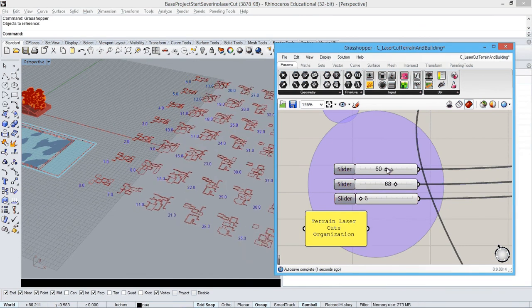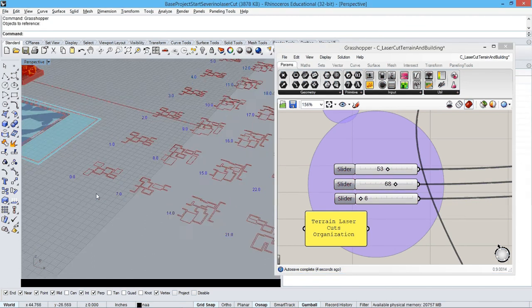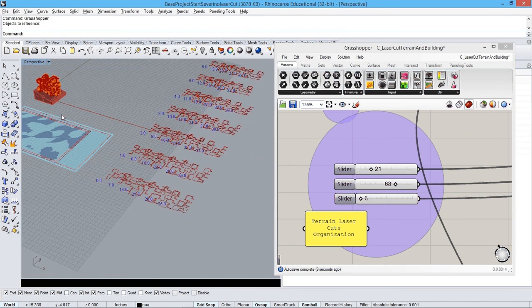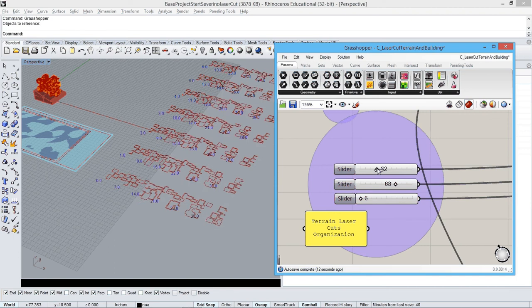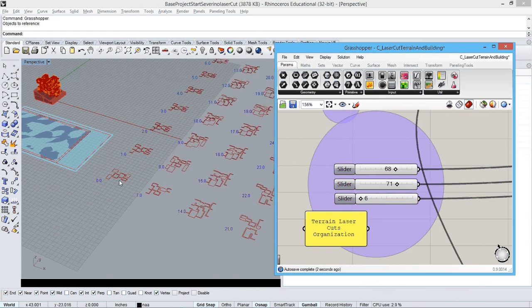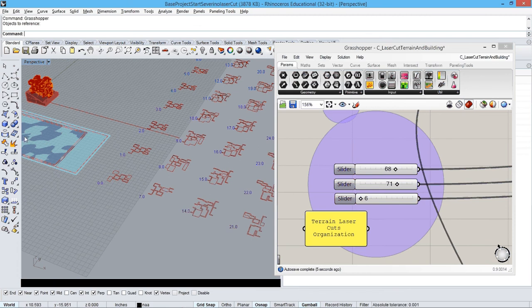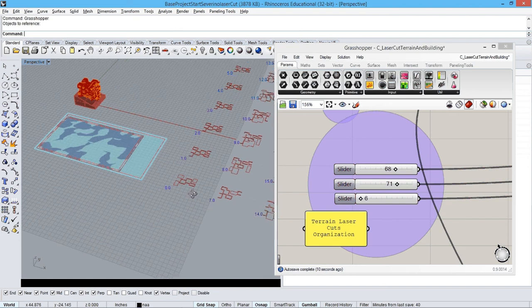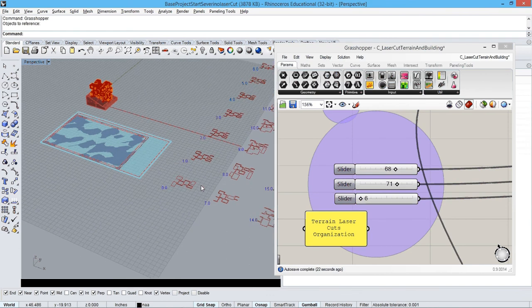You see how this measures the distance between the pieces. If for some reason you have them too close like that, you cannot separate them, you cannot take one to the border, and so on. You need to distance them in a way that allows you to select them correctly after being baked. This is in the other direction. It doesn't matter if it's a big size, because we're going to have to place each of these here. Needless to say, there's another Grasshopper definition that is a little more complex and places these pieces directly into your board size. That's called Rhino Nest, and if you're encouraged, there are some very good video tutorials out there.